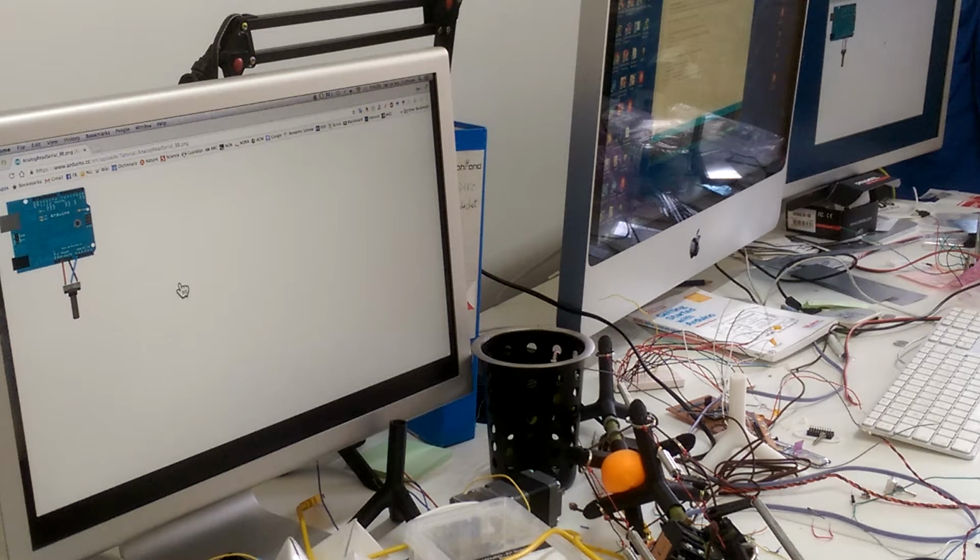These 5 are connected together, but they're not connected to this or to the next one. And then these are all connected together. So you have 2 lines of holes connected together on both edges of the board, and then the rest are vertical groups of 5 holes connected together with a big separation in the middle.